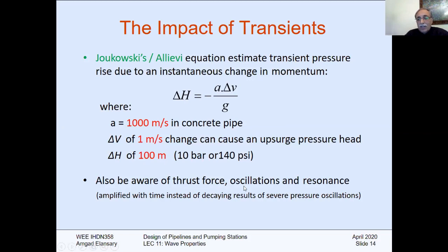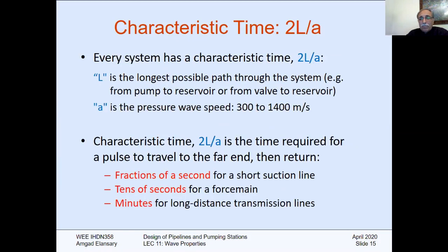The oscillation, the resonance. You can find resonance in the reservoir, which will be amplified. Something will be amplified with time instead of decaying, the result of severe pressure oscillations here. But let's concentrate on the increase in the pressure, which is the Joukowsky pressure here.